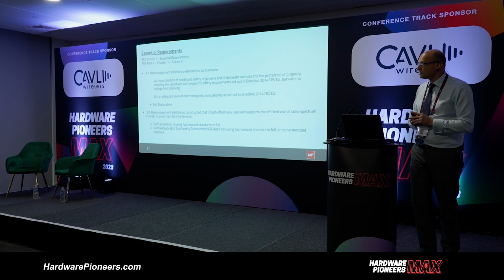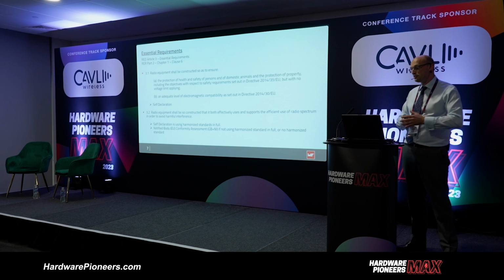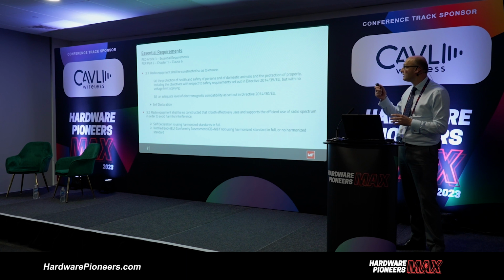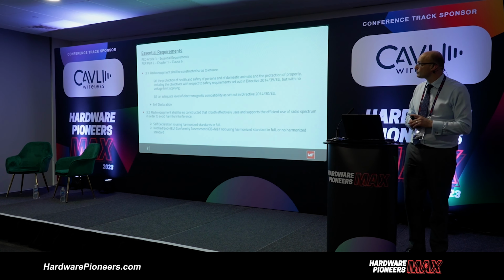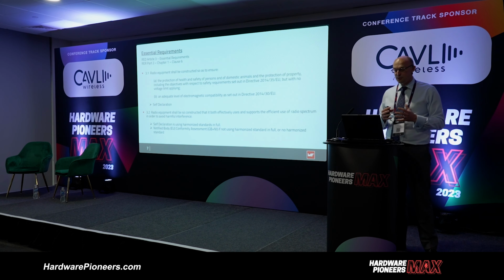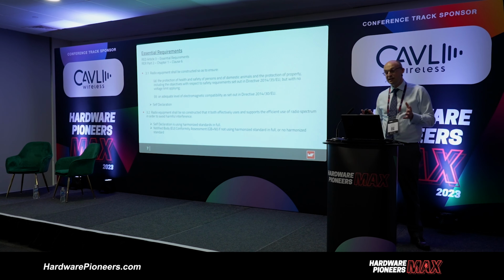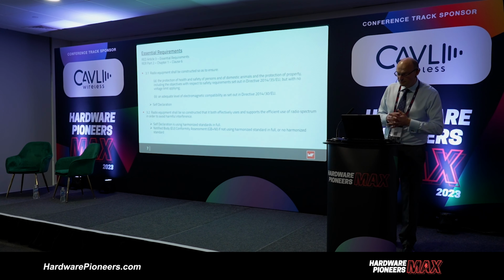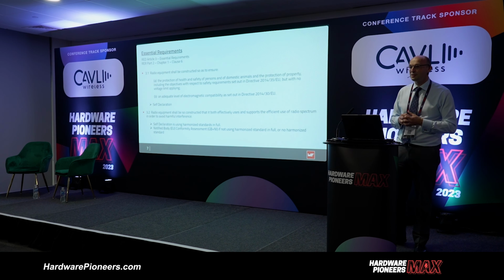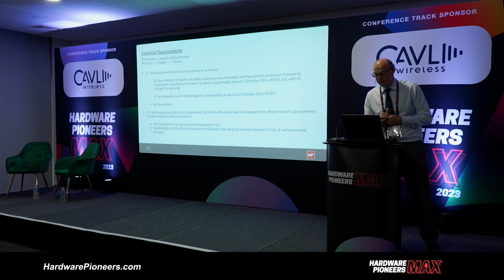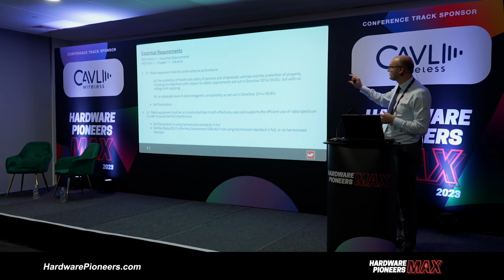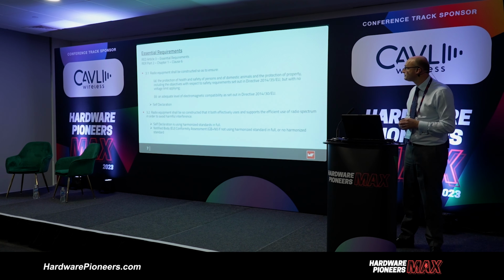So the essential requirements of the Radio Equipment Directive, this is a legal obligation. In this case, Article 3, or in the Radio Equipment Regulations, Chapter 1, Clause 6. So 3.1 is with regard to the radio equipment being constructed to, one, make sure it's electrically safe for the end user, persons, and what's quite interesting, they also refer to domestic animals. I don't know of many directives that actually make reference to domestic animals being protected as well as property with regard to electrical safety, and once again it references the Low Voltage Directive.